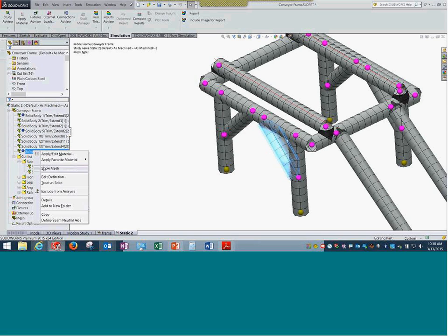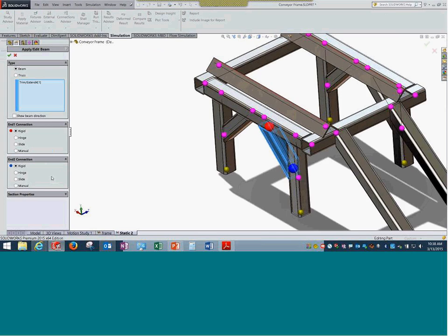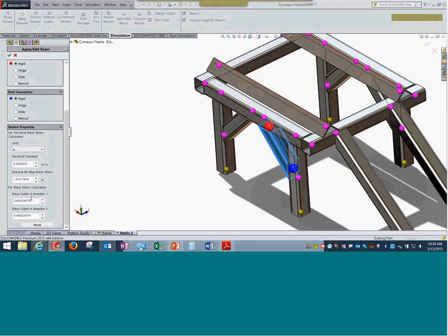Okay, so this is one thing, and I want to ensure I have one more thing. Let me open this definition option. Okay, restriction properties. By default, based on the material properties, the software will take the shear or the torsional properties of a beam. In the past, we did not have this option. Beams would neglect torsional shear stresses or properties.